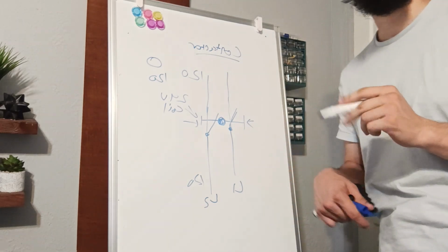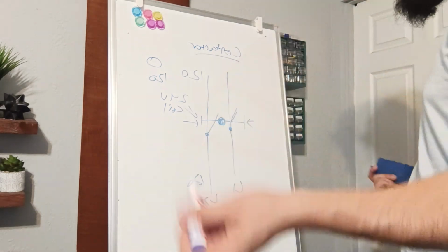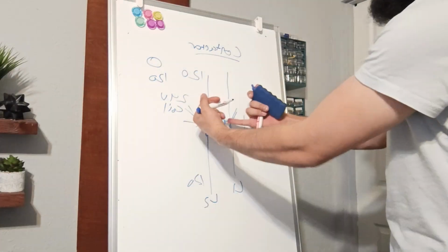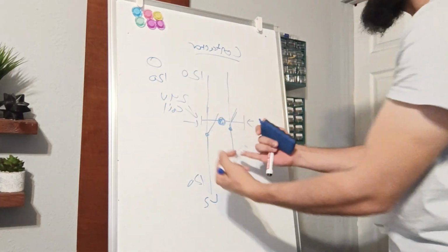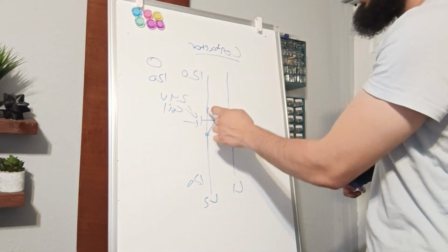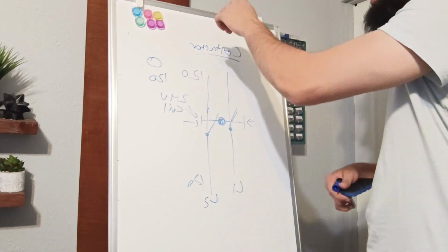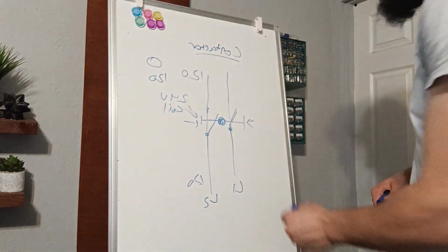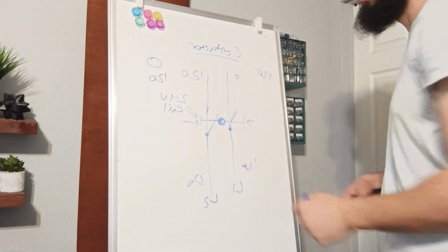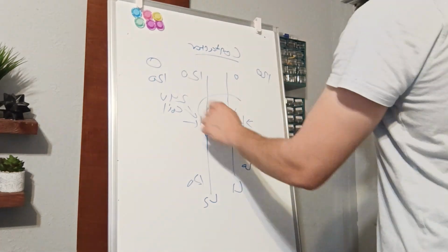So, contactor, electromagnetic switch: it gets electricity to the coil, sucks these contacts in, and then it allows the circuit to close, which sends power over there. So, for example, if you have 120 here, you have 0 here, you'll get 120 on your multimeter. That means the contactor is bad.